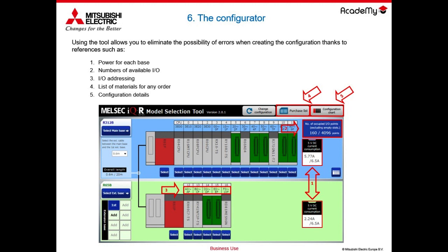So a card starts from 000F if the first card installed occupies 16 points, or from 001F if the first card occupies 32 points, and then always in hexadecimal format in a continuous manner, the addresses are increased.